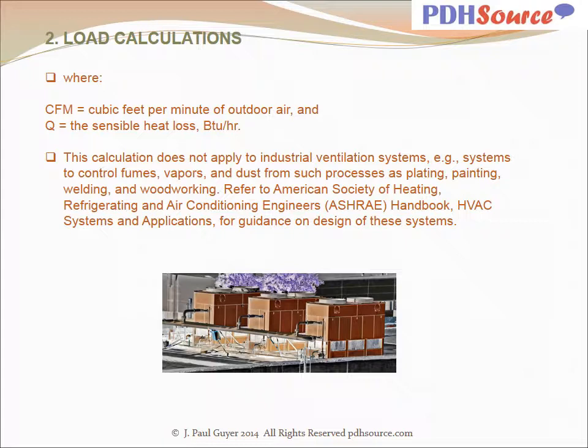The sensible heat is what we talk about when we talk about heat loss. When I talk about heat loss, I will be talking about sensible heat loss. If you're designing an air conditioning system in a very humid climate, and there are humid places in the United States, Florida, some of the East Coast, that sort of thing, but in the largest part of the US, you can ignore the latent heat.